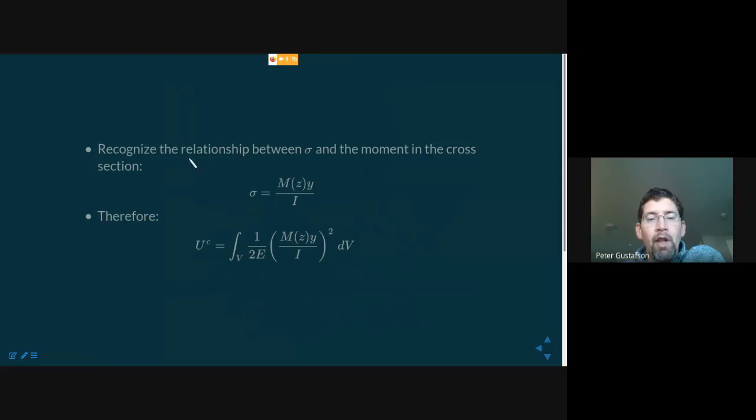Now, recall from our beam bending lecture that we can actually calculate the stress in a beam pretty easily if we can write the moment. Okay, so here is the relationship for this essentially one-dimensional beam with an unspecified cross-section. We're going to say it has a cross-section that gives us an area moment of inertia I. Obviously, it's got a centroid.